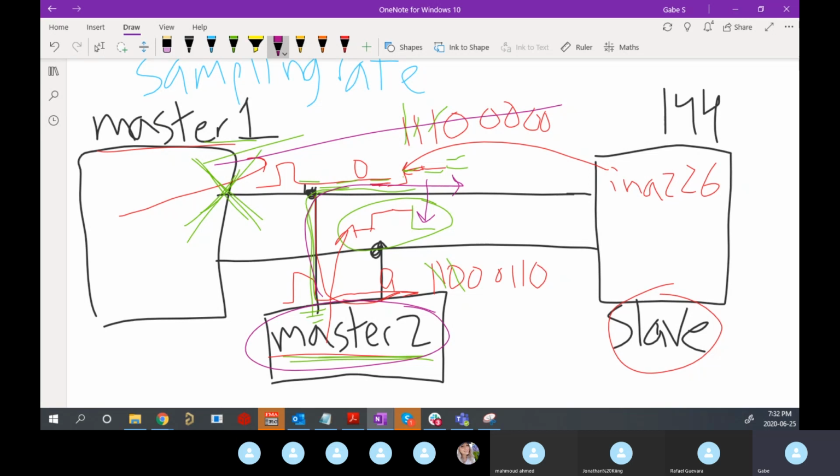And that's why I2C is open drain. There's only one data line. There's only one SDA, and it has to be shared amongst everyone: amongst the slave, amongst Master 2, Master 1, any other masters and slaves that want to talk on that line. And how they arbitrate who wins, who gets to talk, is by making use of open drain.